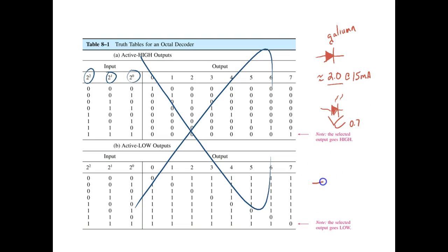So if I was going to power the LED up on a 5-volt supply, I would come up here and put a resistor. If it's a common cathode, then I'm going to turn it on with the cathode, and the anodes will be connected to plus 5 volts. This guy drops 2 volts, so what would the resistor drop? Got to drop all the voltage. 5 volts supplied, the LED drops 2, so the resistor drops 3 at 15 milliamps.